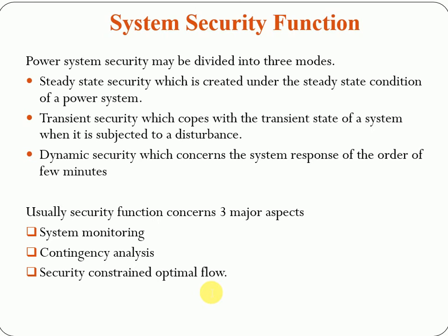In practice, a supervisory control system, which allows the operator to control circuit breakers and disconnect switches and transfer taps remotely, is always combined with such a system to create a new kind of system. This is what we call SCADA, Supervisory Control and Data Acquisition System.